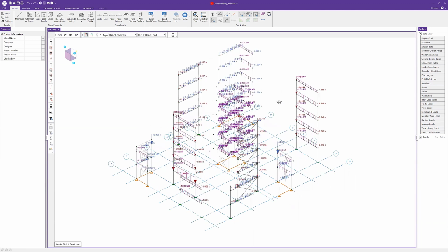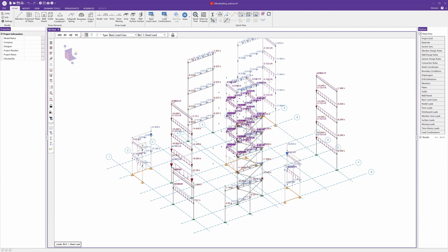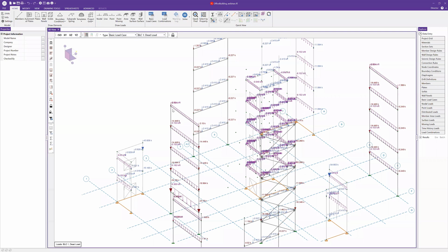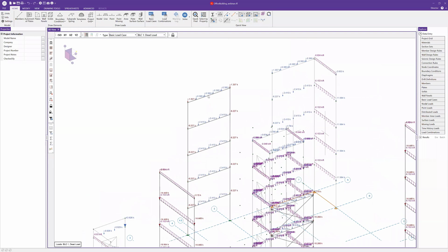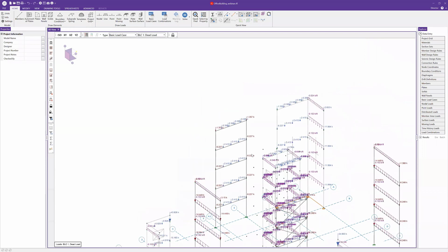So in this particular case, we're looking at dead loads, for instance. We're seeing dead point loads on the edges of frames where a beam or a joist frames into that column or beam. You can see, for instance, over here, our framing direction for RISAFloor was in this direction here. So we have a point load, and they're uniform, which makes sense. So we have a uniform point load in this case that's applied in this location. And so we're getting all those loads. All that load information is tracking from RISAFloor into RISA 3D, and then we'll continue to track it even down into RISA Foundation, as well as into RISAConnection when we look at our loads applied there. So we've got all of that load information.